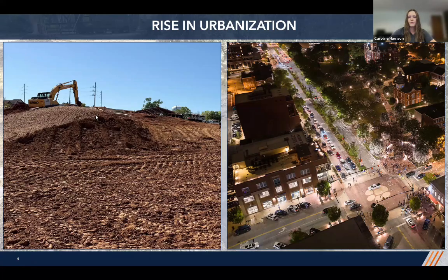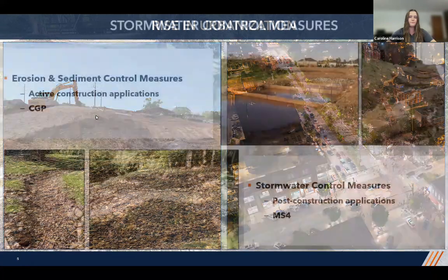Now, on the other hand, our impervious surfaces can increase our volume and also flow velocities of our stormwater runoff, which in turn will limit our infiltration capacity, and can also increase our erosion potential. One other thing to note, our stormwater runoff can also intercept a lot of these pollutants that I mentioned in the previous slide as it is flowing across these impervious surfaces.